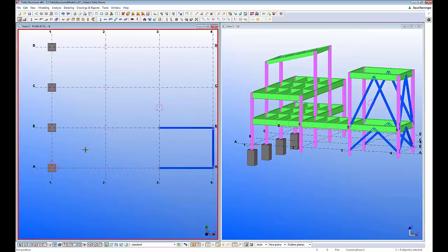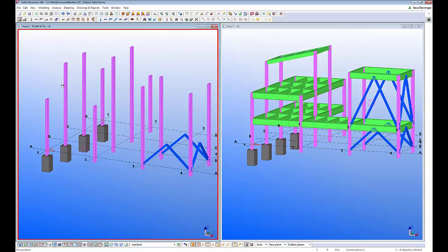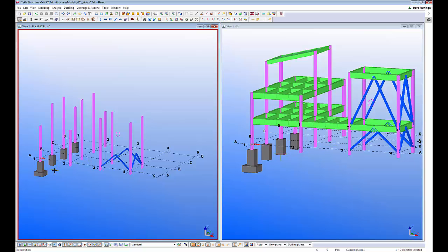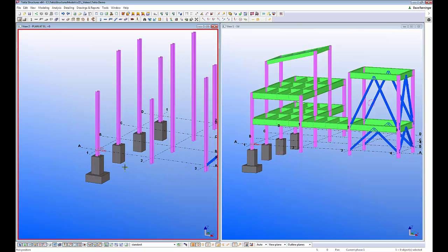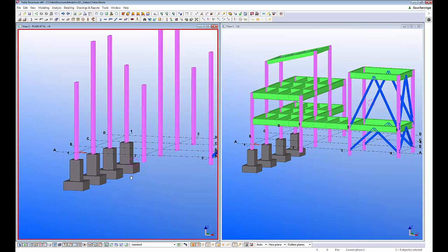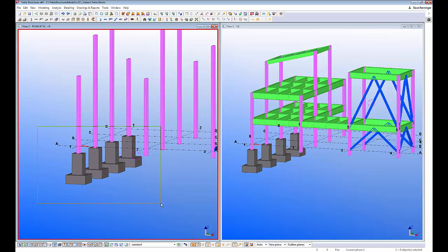In this one, I'm actually going to rotate this Plane Elevation 0. As you can see, all views in Tekla are 3D views. What's nice about these tools, the pad footings and basically our column commands as well, is that it doesn't matter if I pick the bottom of the pier, the top of the pier, or the grid intersection, the properties of this footing are going to dictate the actual top and bottom elevation of it.